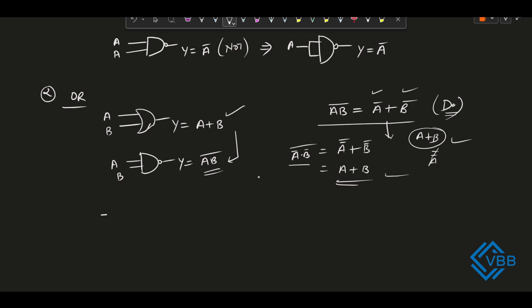So what we will do, we will just complement the input using the NAND gate implementation. Okay, that we have discussed now. So we will connect these to the NAND gate, and here we will get A complement and B complement. Okay, so that we will connect to our NAND gate and we will get the final output expression as A plus B, that is all we want here.